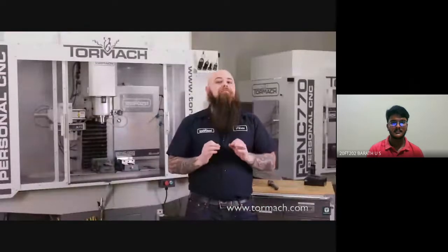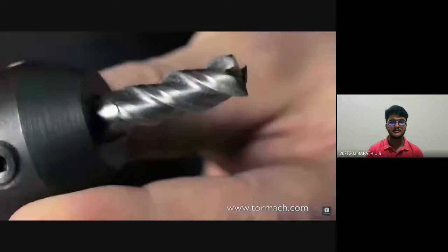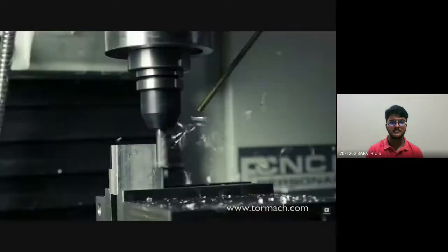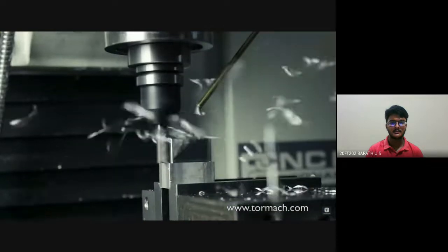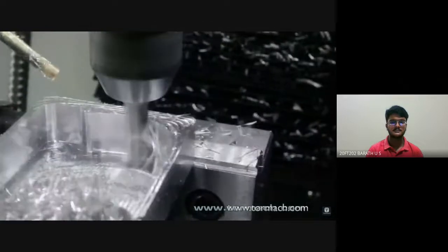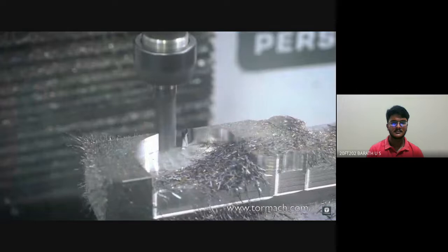Carbide tools can get much hotter than high-speed steel, and therefore are more susceptible to thermal shocking, meaning different parts of the cutter expand by different amounts, causing the cutter to chip, break, or even explode. This means that you typically want to go light on the coolant while using carbide tools. High-speed steel is more flexible, so no explosions, but it will still get hot, so flood coolant is recommended.